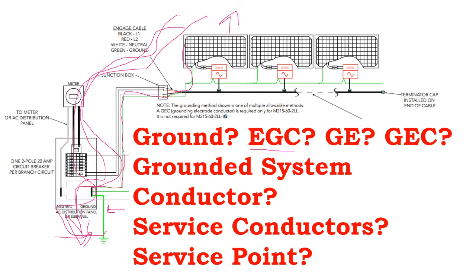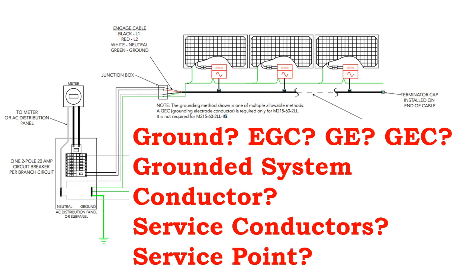So just because you're installing these equipment ground paths is not going to ensure safety. What we're hoping in that situation is that during that ground fault enough current goes through the ground path to open up the breaker, and that things don't burn up in the meantime.